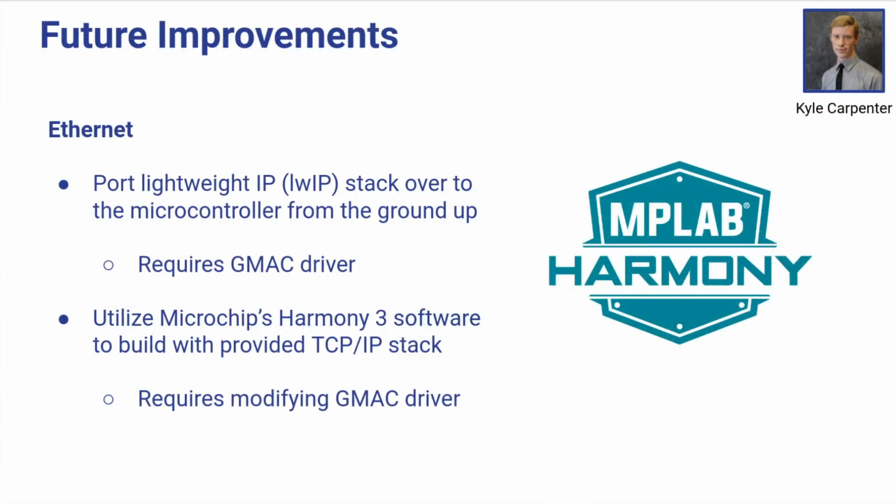For future improvements for the Ethernet, we could port over the lightweight IP stack to the microcontroller from the ground up. This is another TCP/IP stack, similar to what's provided by Microchip. However, it would take a while to port over just because there aren't any existing APIs or drivers that would make it simple to get started.